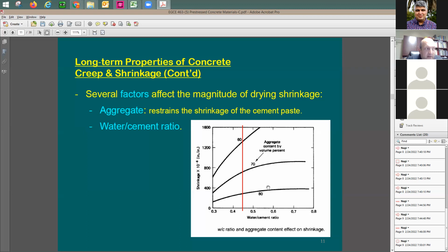So generally speaking, you'd like to go with less shrinkage properties when it comes to the aggregate. And we do this. In the concrete mix design, they give you the properties of all the aggregate, and then they give you the shrinkage properties. And I showed this to you. So the shrinkage characteristics or properties of the aggregate are going to be very important. The aggregate type and the amount of aggregate, these two items are going to be very critical.